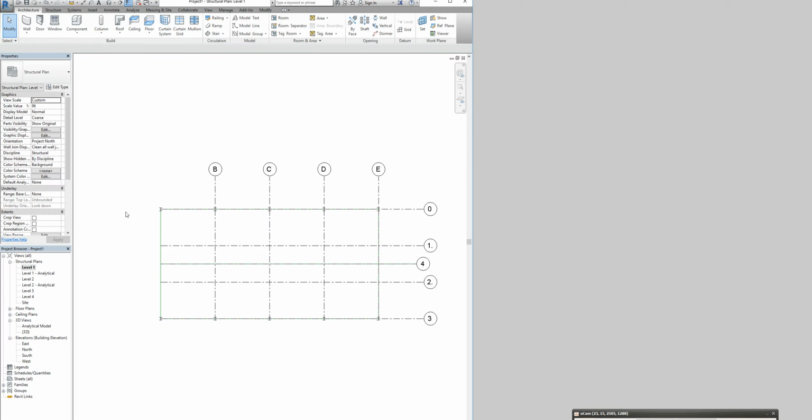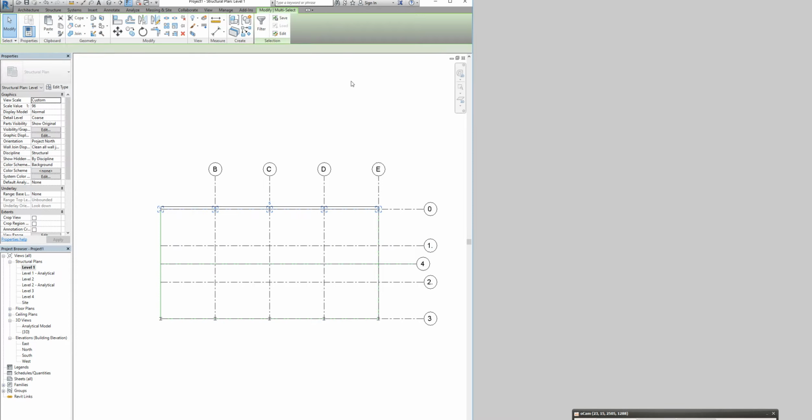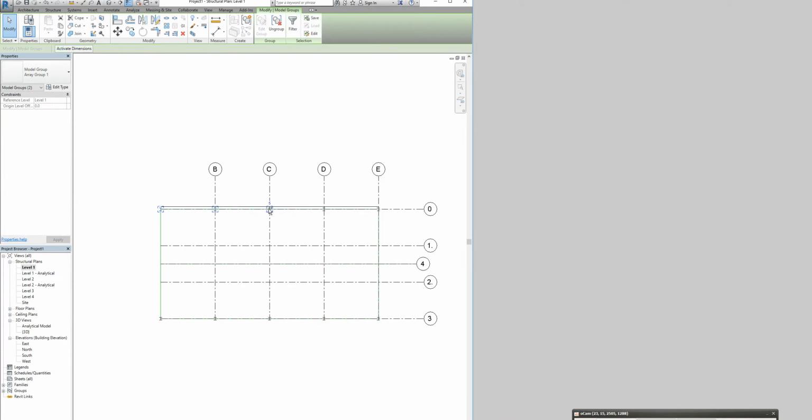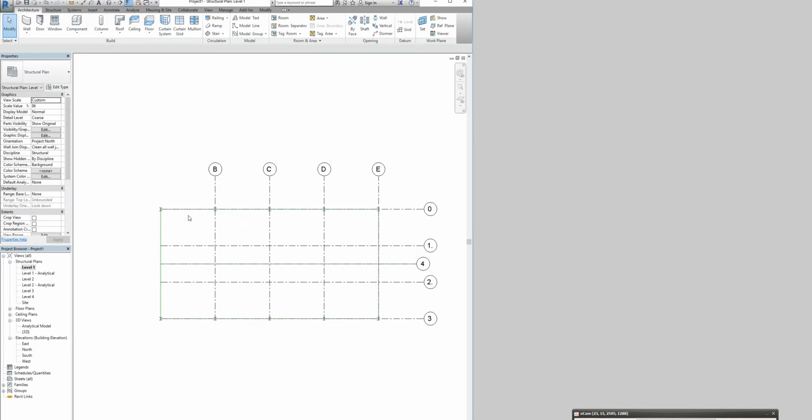Alright, and ungroup columns, so same thing, we just go here. We have to select them individually probably, because otherwise it's selecting all the boundary and everything. So ungroup, same here, we select all the columns and ungroup. To select everything, I just use the control key, like many elements.